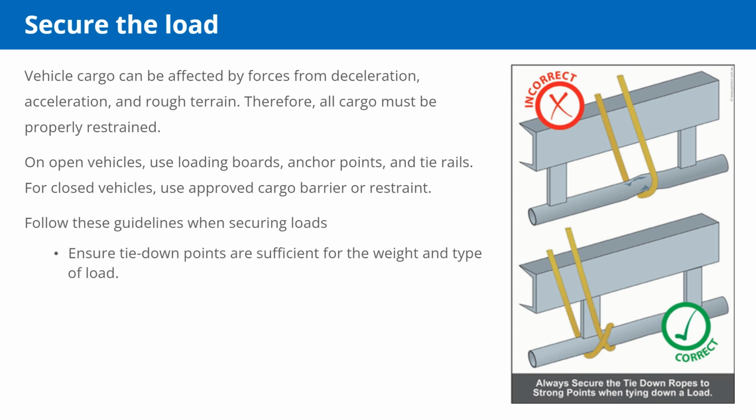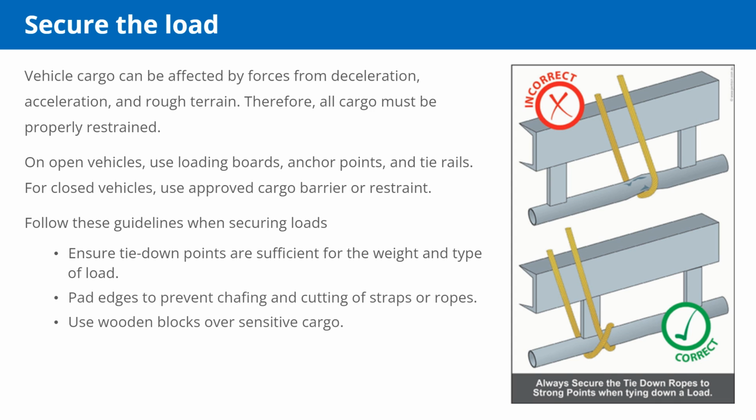Ensure tie-down points are sufficient for the weight and type of load. Pad edges to prevent chafing and cutting of straps or ropes. Use wooden blocks over sensitive cargo. Avoid over-tensioning restraints to prevent damage.